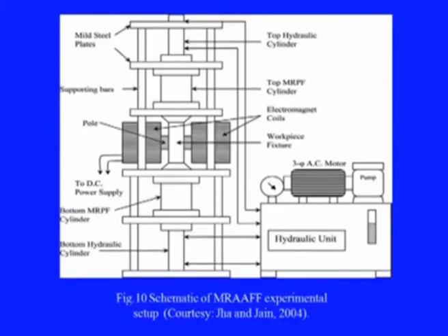In this process, rheological properties of an abrasive laden medium, also called smart magnetorheological fluid, is controlled using an external magnetic field. It imparts better control of the process behavior due to better control over abrading medium's rheological behavior. This is the schematic of this process.